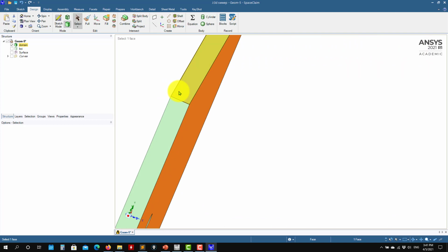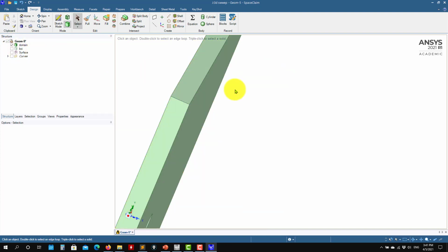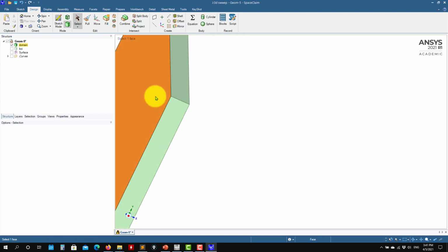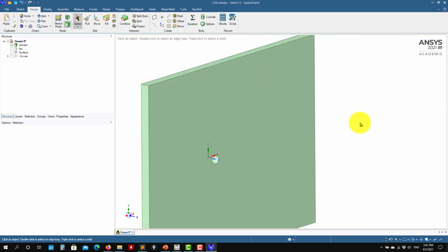Actually, many commercial software packages don't take surfaces like this for 2D. To do a 3D case, you need to use an actual 3D volume and then an extrusion with one cell, and then set symmetry here. In some cases they have an empty boundary condition. So I prefer to work like this. I will show you the two meshes, and then it will be up to you to choose a method. The cell count will be the same. Honestly, this makes your post-processing for visualizing easier. It will make things easier.